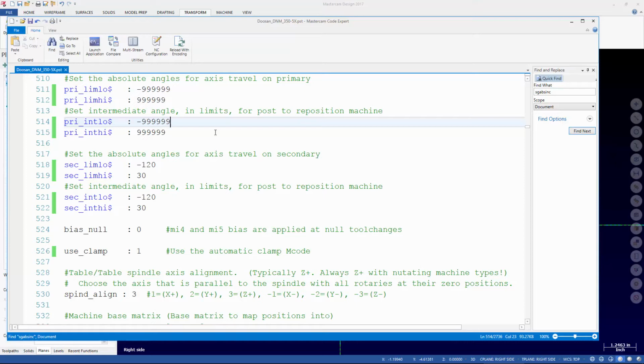At the tool change events, when we output rotary positioning, typically, whether we're doing a 5-axis toolpath or a 3-axis toolpath, there's always an initial positioning, right? So we're going to rotate the rotaries to their proper spot. Let's just do something real quick here.